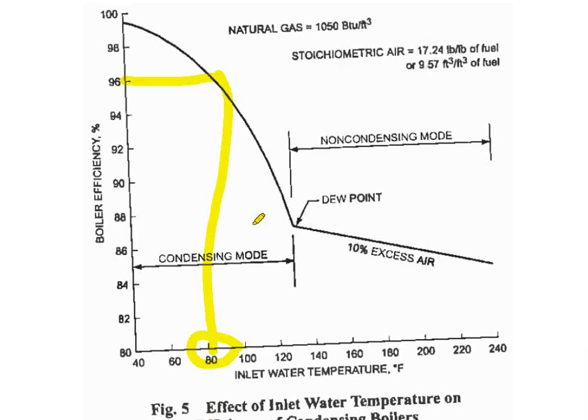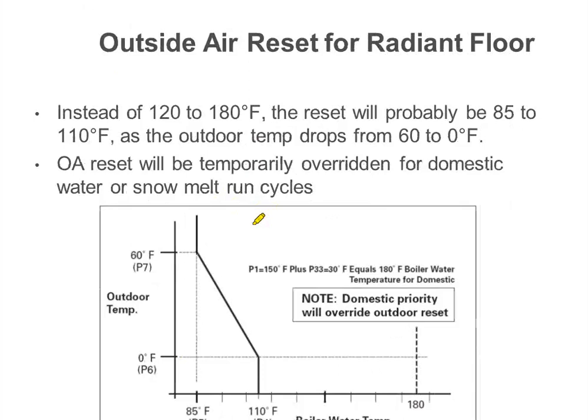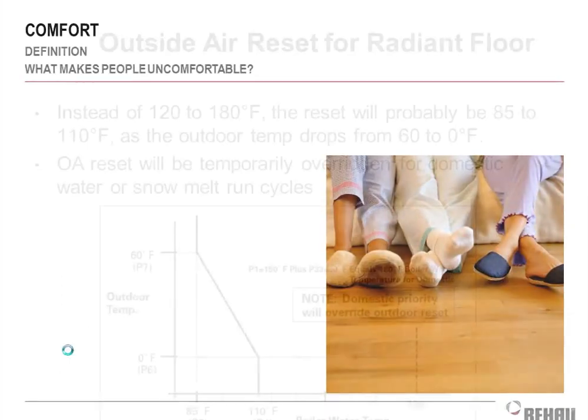So some of the boiler manufacturers, when you look at their literature, they'll tell you what the thermal efficiency percent or the AFUE percent rating is, and then below it they might put in parentheses, hey, this is a 94% efficient boiler, parentheses, 98% on a radiant system or something like that, because they know they're going to be operating at a cooler return water temperature, and hence making it more efficient. So that's one of the many reasons why a radiant system is more efficient to operate than a traditional hydronic system would be. We'll talk about a few other ones as we walk through here.